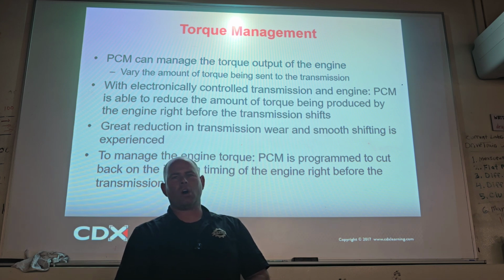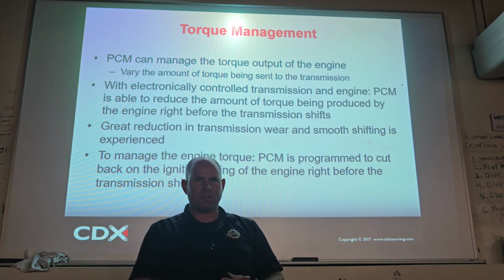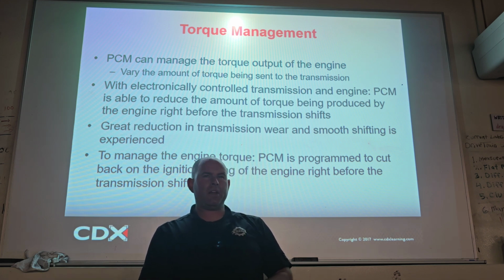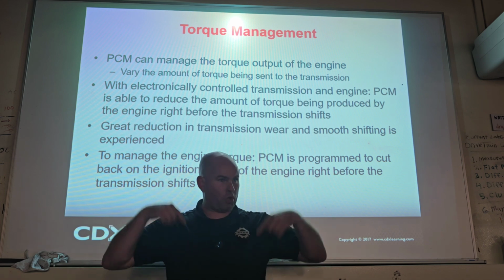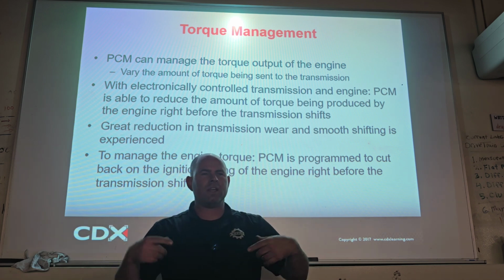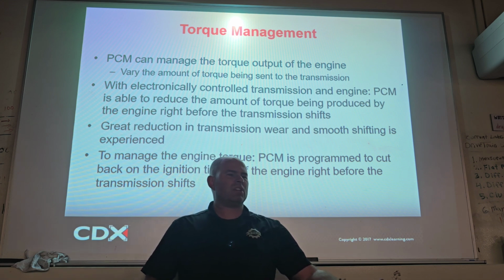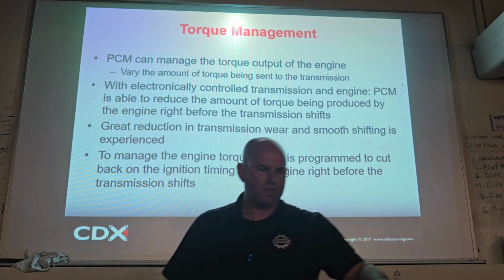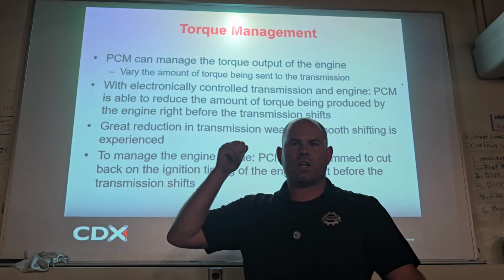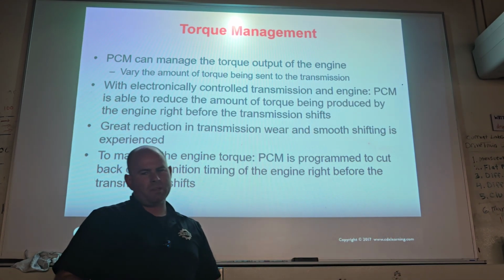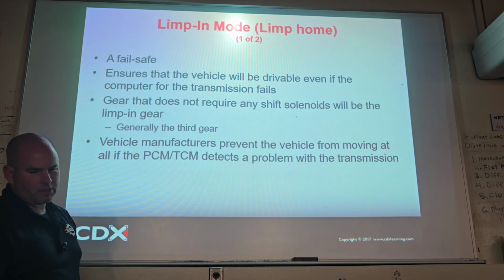And they have their trucks all tuned, all the torque management's off. There's no protections for that transmission. And also, it's kind of hard to keep a transmission cool when you're doing basically a stall test permanently with your back tire just barely turning. And how much air is flowing through the radiator? Nothing. And how much is that air cooling your transmission cooler, which would be in the radiator? Not much, right? So some of these electronic protections, they probably should be there if you want it to last. If you want to take it off, go for it, but don't be surprised.